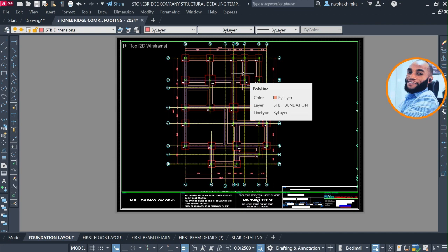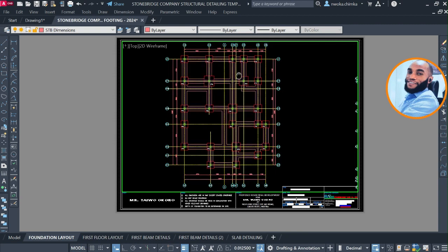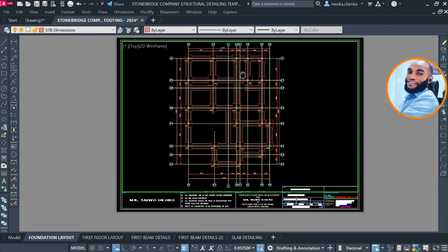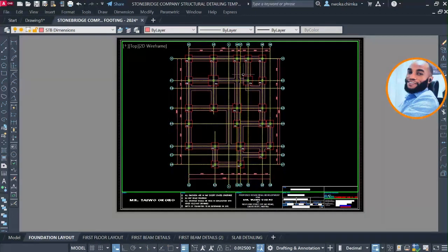As you can see, all our drawings have now been entered on this template for printing. We have transferred the drawing we have done so far from our model space down to paper space here for printing. So I'll quickly place it here and arrange it a bit. Once I've done that, I'll press PS, which means to go out from this environment, and press enter.